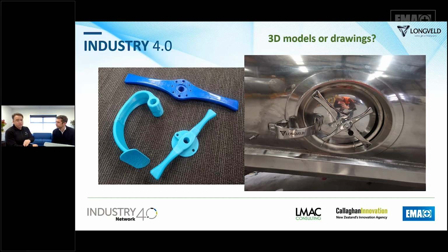Right. And this allows us to make something cheaper. We didn't need tooling to create those model parts for the casting. They use the same process: they make a ceramic coating over it and then melt the material out, and then they use that as a mold for casting. Great, that's awesome. The main benefit is that you can do it quickly and create these very complex parts as you require them, test them, and then get them cast, without any tooling investment. Okay, awesome. Great stuff, great stuff.